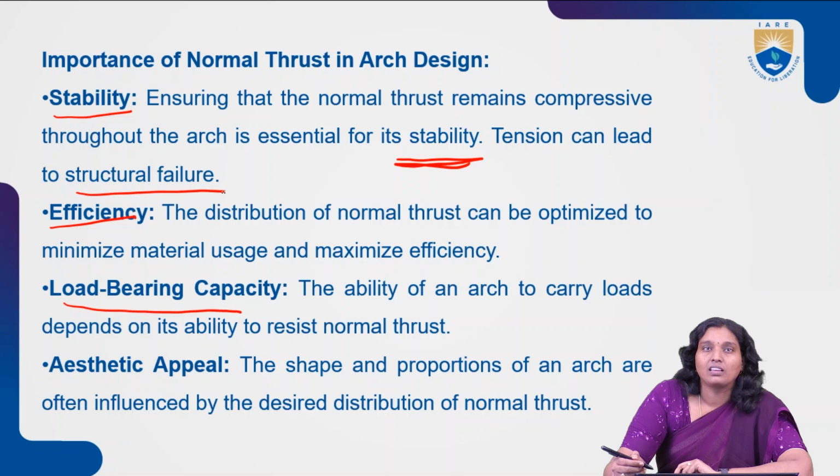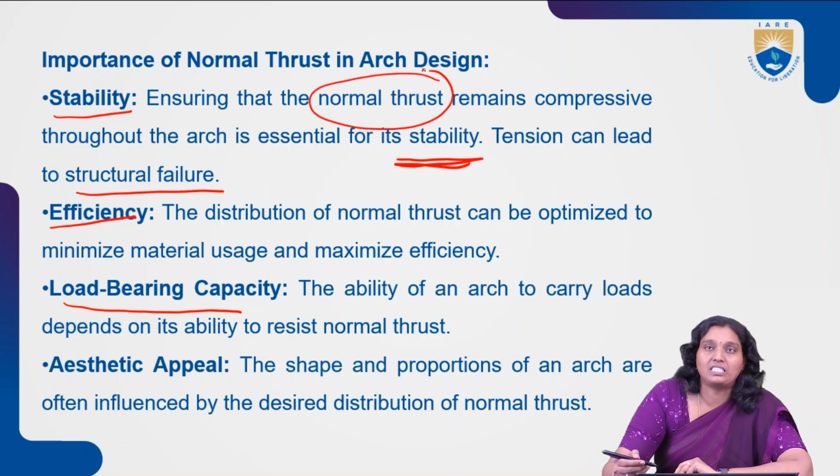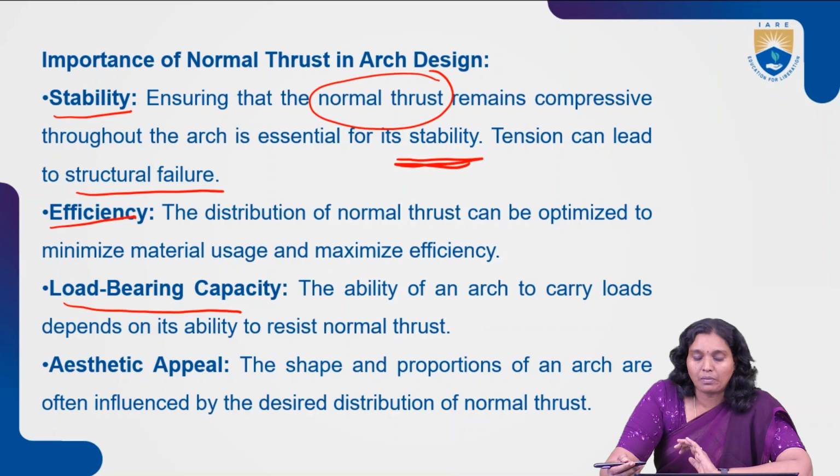That's why understanding the normal thrust plays a crucial role in arch design. Once tension is there in this compressive structure, it leads to structural failures.